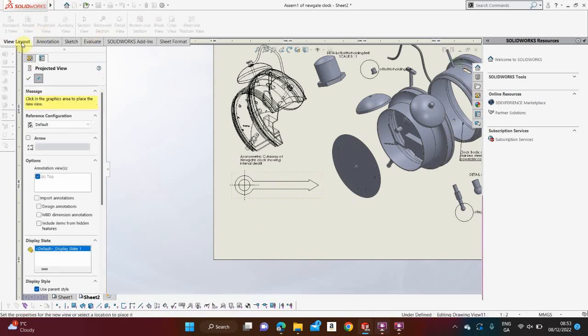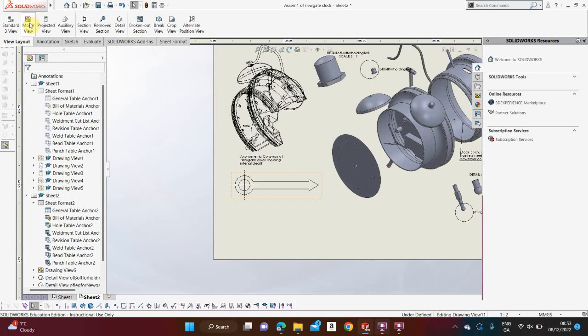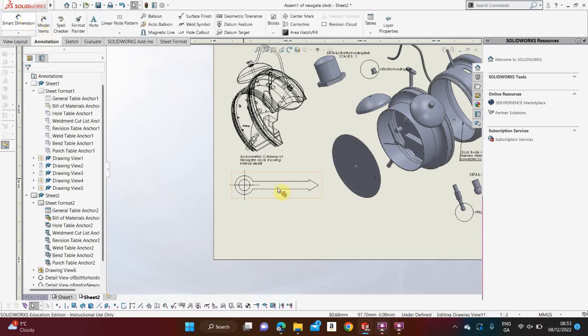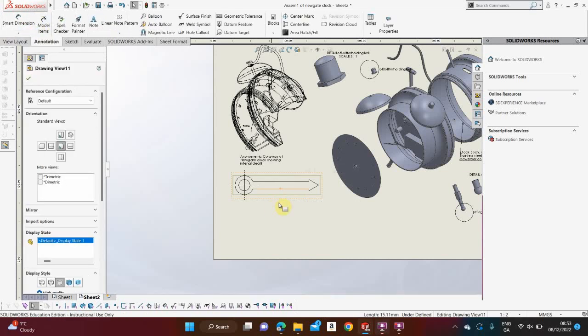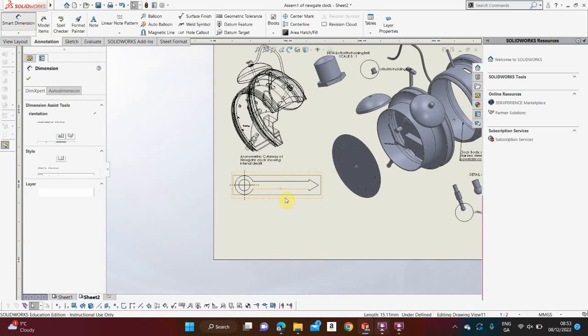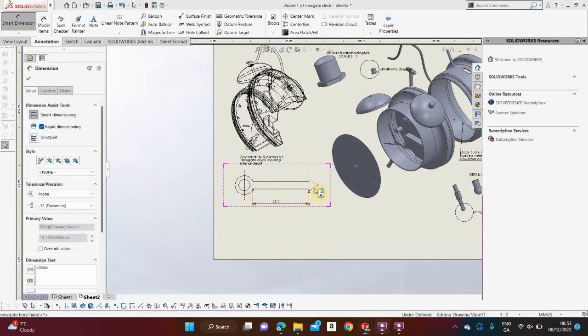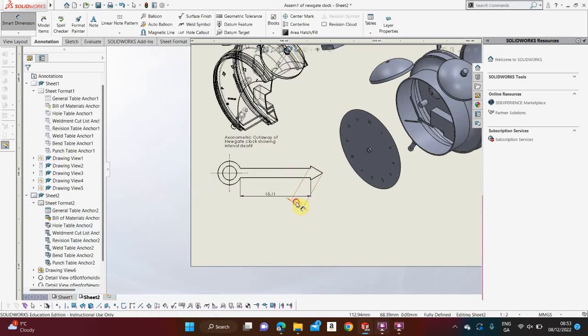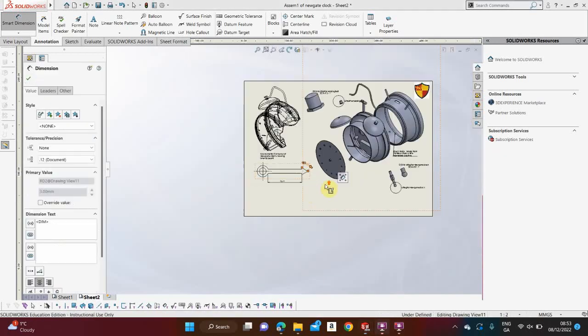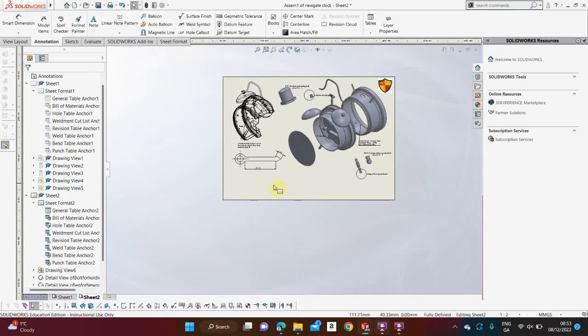And then because it was a small part, you can now go to annotation, smart dimension, and you can dimension that small part here now on this sheet. Exactly what height it is, what the angle is between them two pins maybe, stuff like that. Okay. Just be conscious, keep this bottom left-hand corner empty for printing, and that'll make sense when we print it out. But really everything else, roughly where I have it, is what you can do.